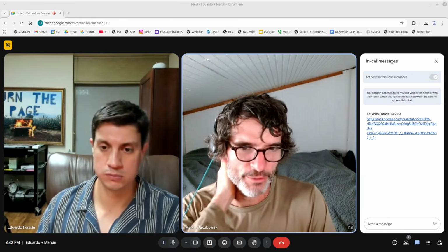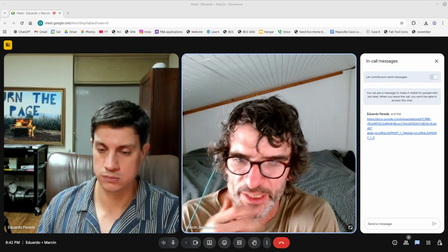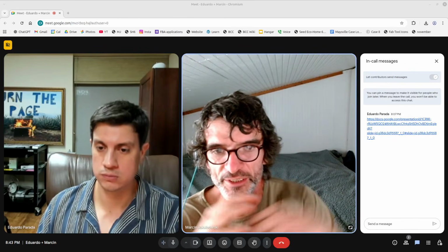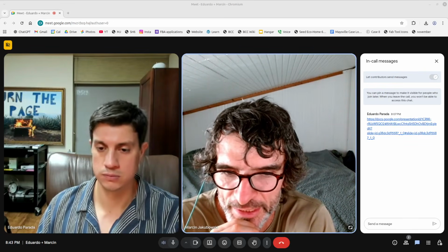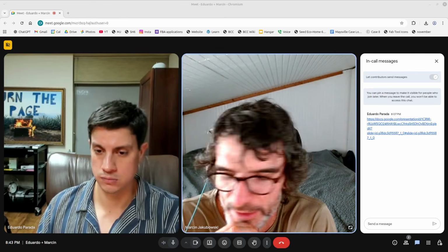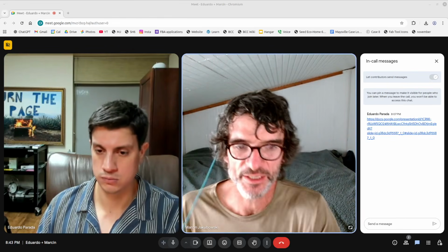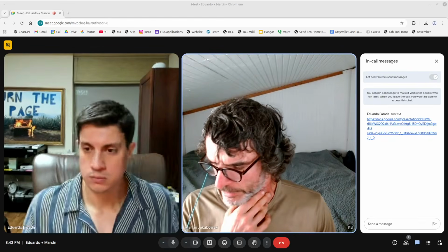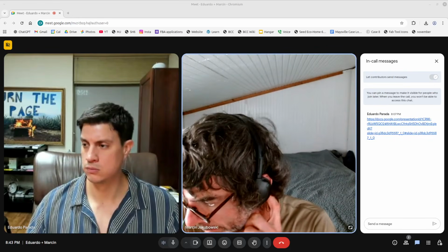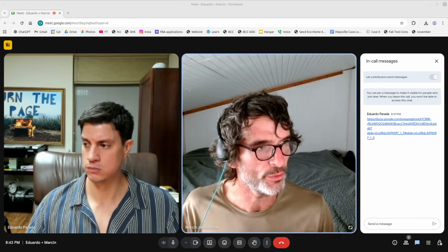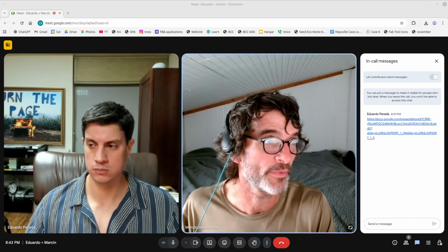1 millimeter. The first thing I want to know in this project is how quick can I print one of these pots if they're a single layer, 1 millimeter thick? That's a good assumption because you can definitely print like that, and 1 millimeter filament is common. 1.2 is common. Above that, it gets less common. But let's say even 1.2, or even 0.8. 0.8, we've done a lot with. We actually liked to do it. Let's just say 0.8 millimeters.